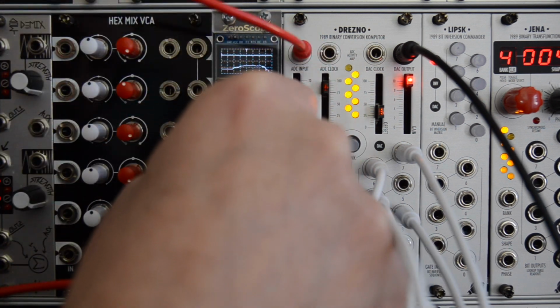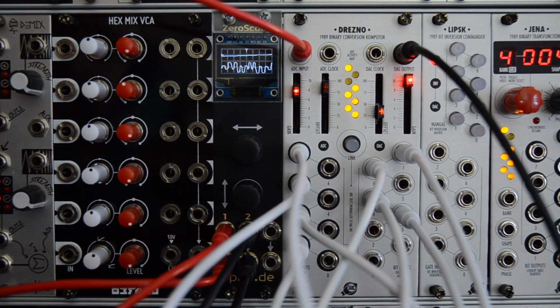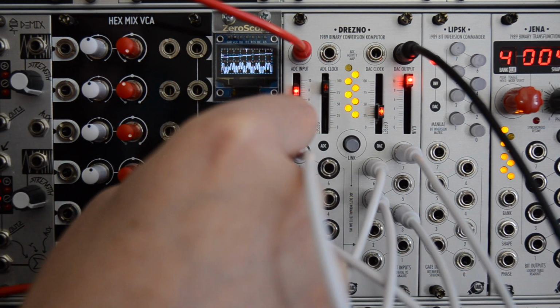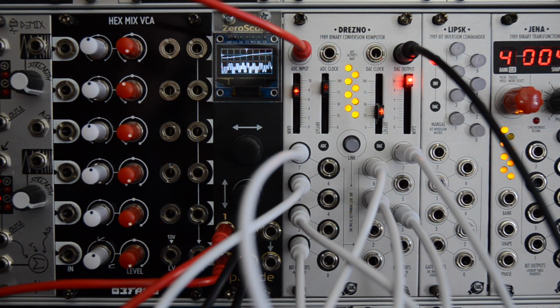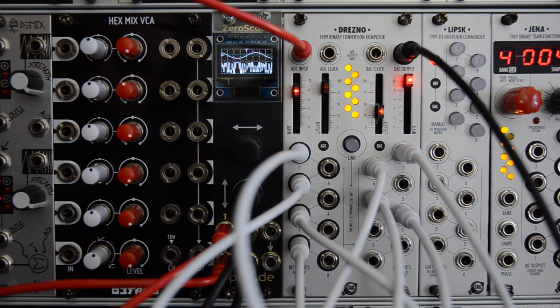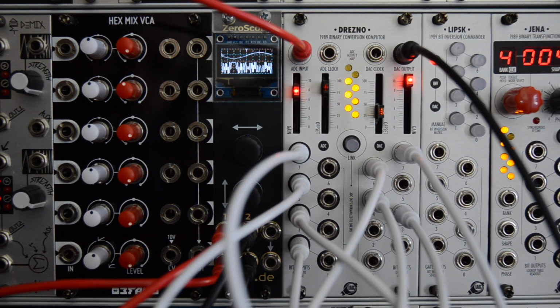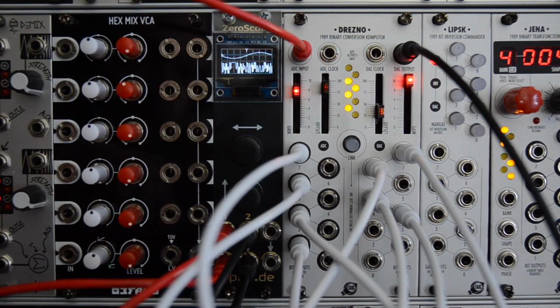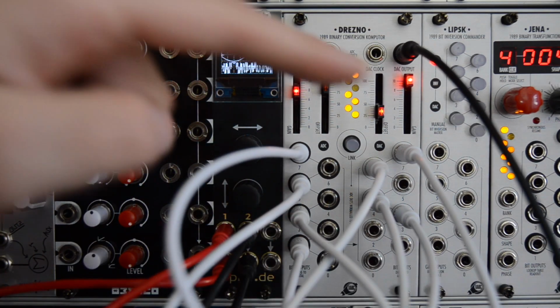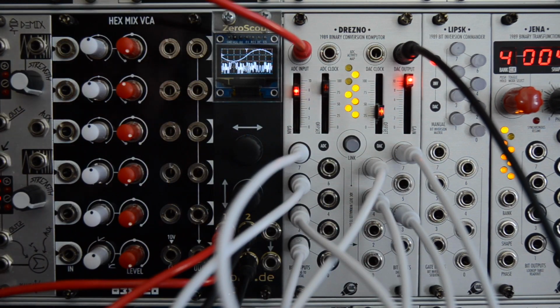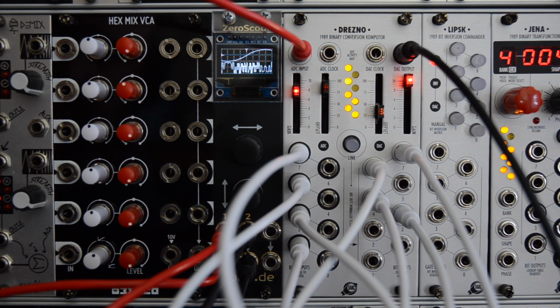Even though my scope isn't having it, there really is some kind of LFO getting through, as you can hear. Please keep in mind that we're currently listening to an LFO. In this mode you can clearly see how the LEDs are changing, thus the gate outputs of the input stage are rapidly changing. Patching these into different bit inputs on the output stage results in audio rate oscillations, even though I slow the sine down really low.